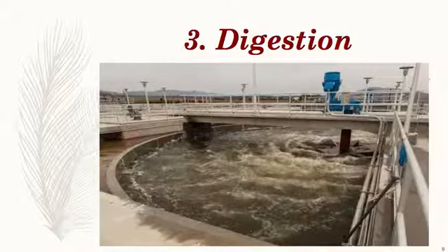Digestion. Many sludges are treated using a variety of digestion techniques, the purpose of which is to reduce the amount of organic matter and the number of disease-causing microbes present in the solids. The most common treatment options include anaerobic digestion, aerobic digestion, and composting, which can be carried out by a very large number of microorganisms. So sludge digestion offers a significant cost advantage by reducing the sludge quantity by nearly 50% and producing biogas as a valuable energy source.